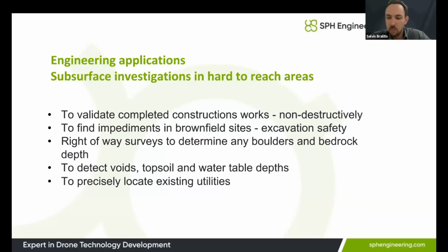Something else that we've heard people are using the GPR for: say you have a construction project for a pipeline and you want to do the subsurface mapping, the alternative is to do boreholes along the right of way. But obviously you can't do it every single meter, so a drone is a good alternative for flying and actually picking up on any potential boulders in the way that were not mapped with the boreholes, or sudden bedrock changes, and that would mean you would have to readjust your designs for the pipe supports or similar things.